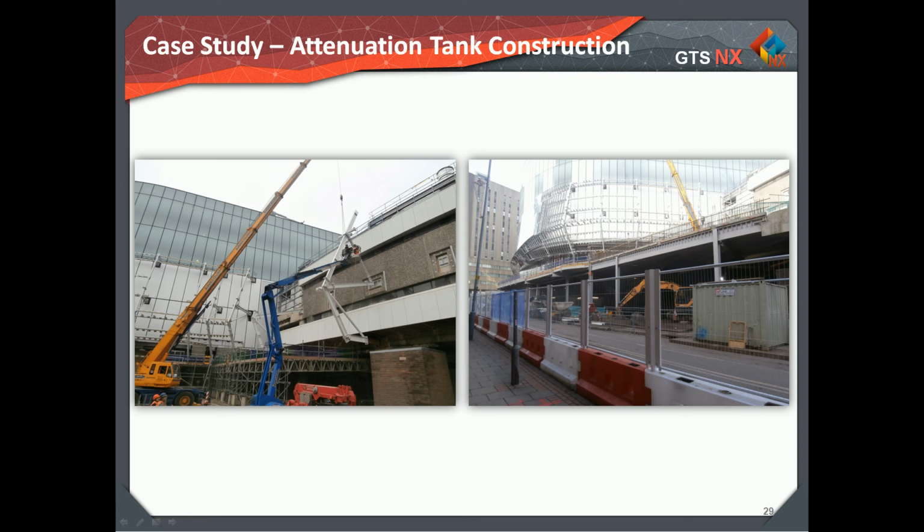Due to construction program and importance of installation of facade works on time, the sequence was to install CFA piles, then the steelwork and deck to be constructed to provide the required access and platform for mobile cranes, spider crane, and then the attenuation tank to be built underneath whilst the other construction activities progressed on the steelwork deck.